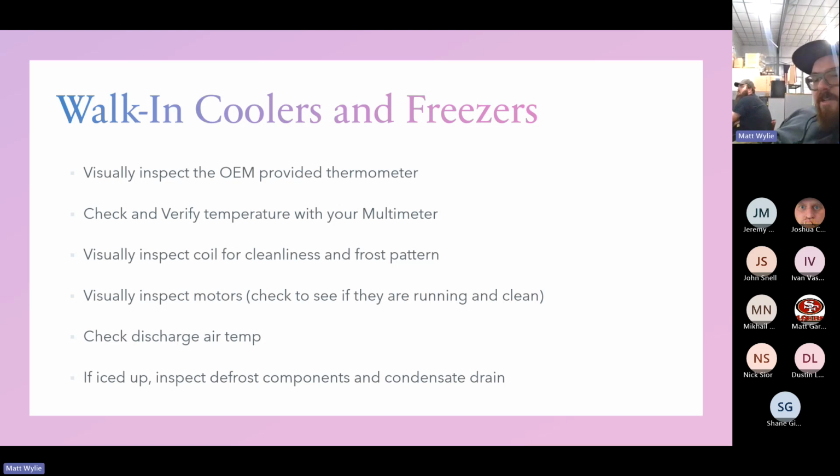If you're doing maintenance, any motors you see that have dirt or oily stuff leaking or whatnot, mark that down, because it's going to go bad and go out, and that could save a trip, save a customer an overtime charge or weekend charge.